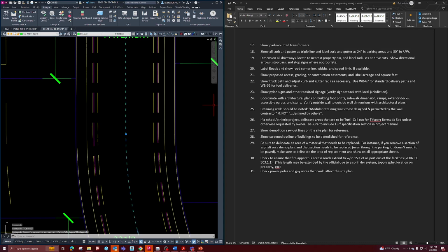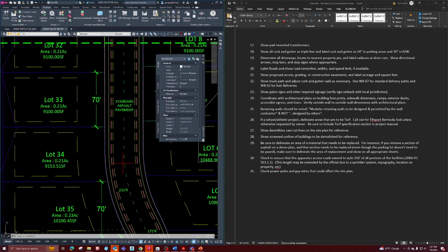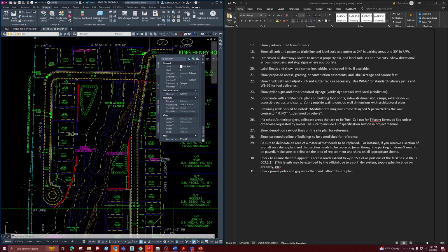And over on your properties tab, you can change your line type scale to make it generate longer line types, or if you want it to have the dashes more frequently. So we'll try like 2. So that looks pretty good for the road center line right there. And you'd want to go through and do the same thing for each road.